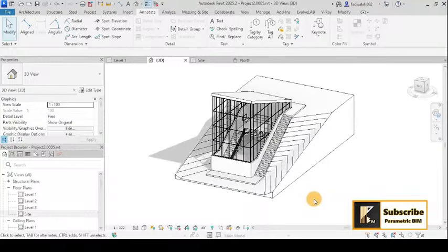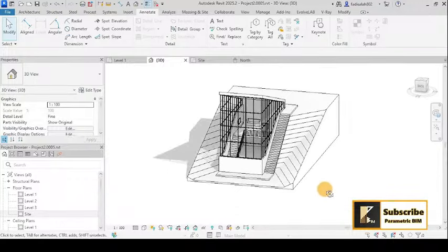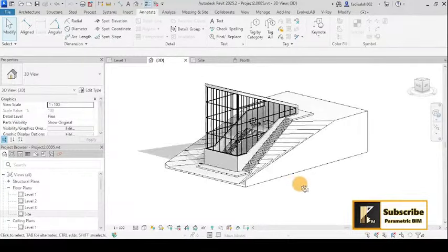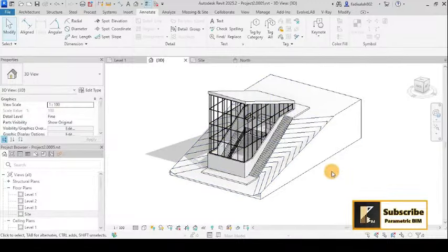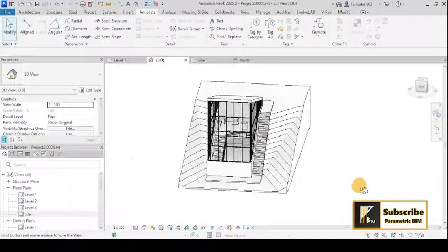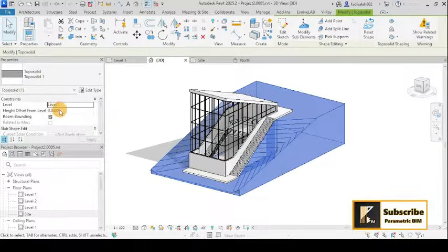So these are the basics of the main difference between how to deal with the Toposurface or the Toposolid. We will talk about this more and more to see which is better, Toposurface or Toposolid. And now, let's also talk about the material. As you remember and as you watched in the video, once I select that, I can change the material from the properties here, but now this does not exist in Revit 2024.